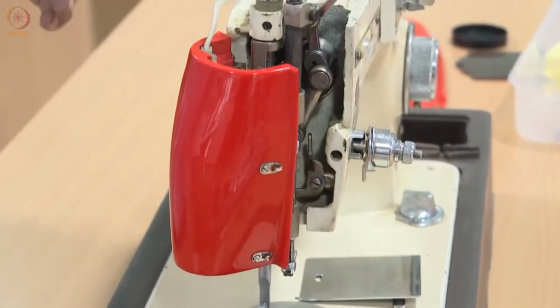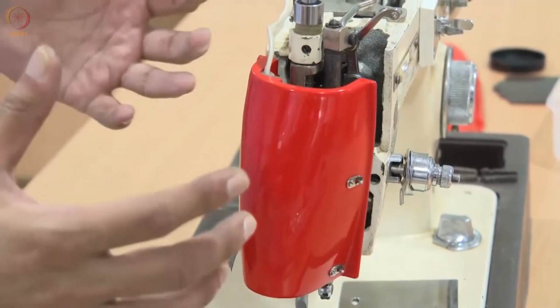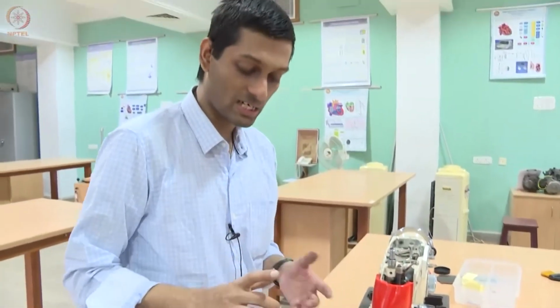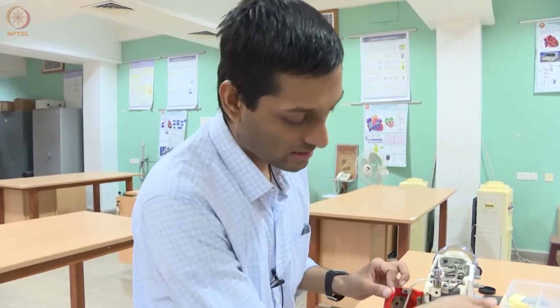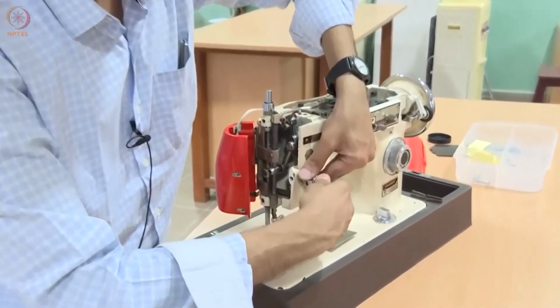You can understand the system is calibrated such that the tension in the string is always maintained within a certain specified level. Which means you have to advance the thread at a specified rate depending on the pitch that the user sets, right? And the tension can be regulated by the screw here.